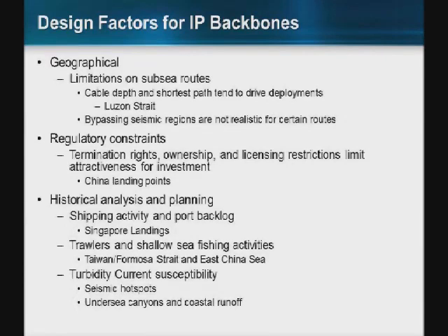You can also do some historical analysis and planning. You can look at particular markets that have a high degree of shipping activity. Singapore is notorious for this. You have a large port backlog, a lot of ships coming into the area. They can't get any access to the port. They're waiting their turn. They'll drop anchor. So in that area, the vast majority of cable faults and outages are typically anchor drops from shipping activity. And again, you can look at other routes in terms of crossing certain shallow seas where there's a lot of fishing activity.